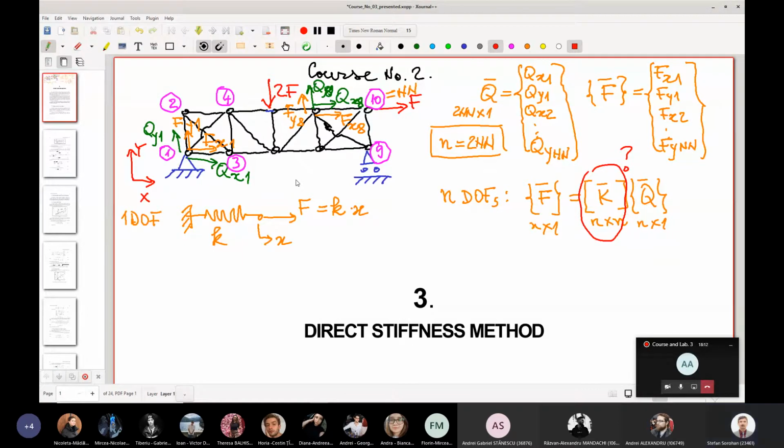And now, let's go back to the structure, and let's imagine that this structure is built one element at a time. If I take a generic element here, I told you that a typical element has an index E. So we take this typical element, which has an area, so the area of this element will be A, index E. The length of this element is LE. The material for this element is also known, so we know the Young modulus for this element.